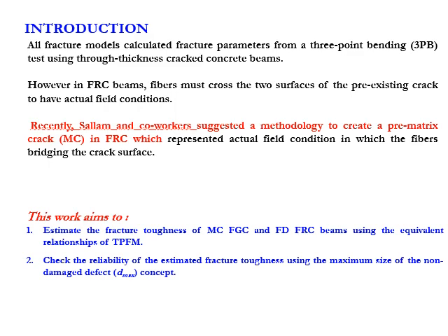Using this methodology, we will estimate the fracture toughness of matrix cracked functional graded concrete and full depth fiber reinforced concrete beams using the equivalent relationship of TPFM. Then we check the reliability of the estimated fracture toughness using the maximum size of the non-damage defect concept.